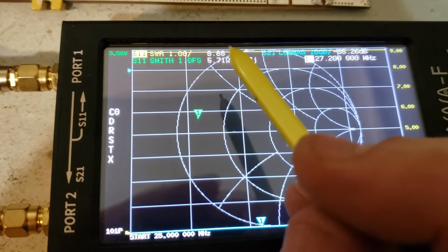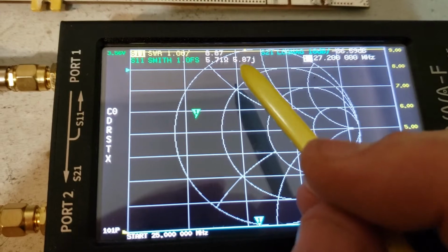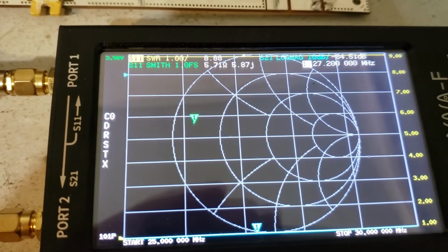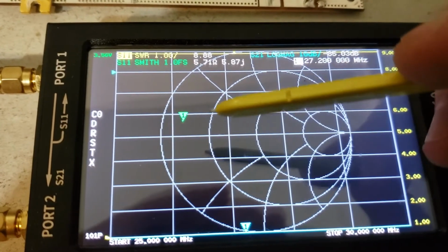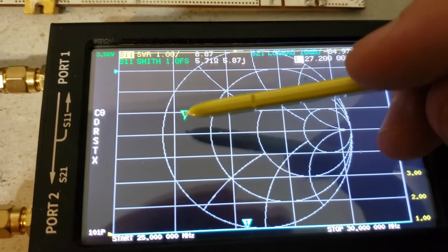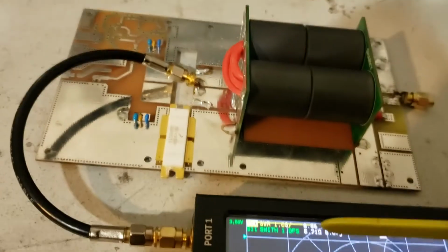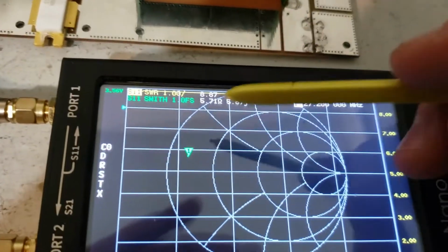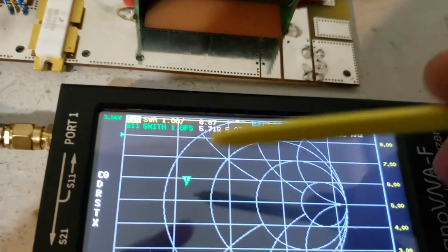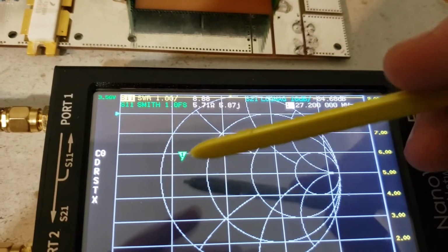So in this case, the impedance that we're seeing right now is 5.7 ohms, 5.8 with positive J component, positive reactance. So right now we're seeing basically 5 ohms with a whole bunch of inductance. That's what this point is. Just from my personal experience, that's actually not too far off for that LDMOS chip right there. That impedance is actually really pretty close to what this sucker likes. But for, say, a Toshiba, this impedance is pretty far off.